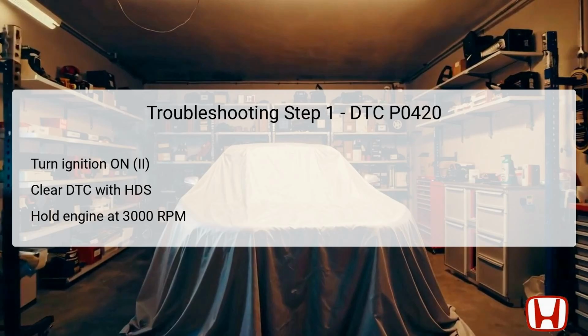After clearing the codes, start the engine and hold the engine speed at 3,000 RPM without any load until the radiator fan activates. This action ensures the engine reaches a sufficient operating temperature, crucial for an accurate diagnosis.